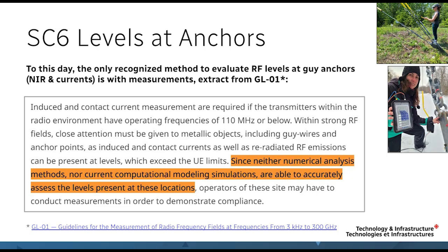Contact currents: when you touch a metallic energized structure, you must not be overexposed by the current that flows from the structure to your finger and through your body. There are certain levels of current that are allowable for humans to touch and not be overexposed by the shock of the contact.